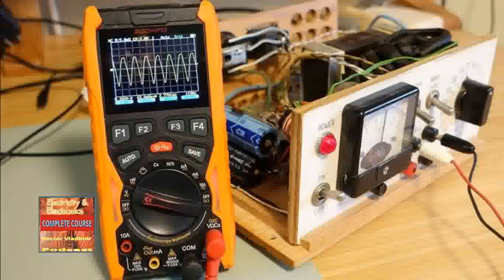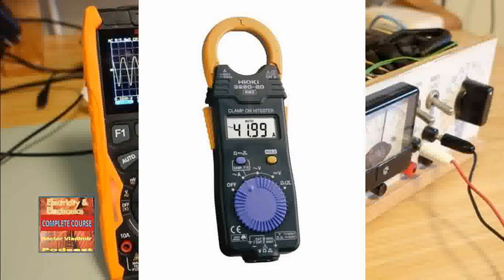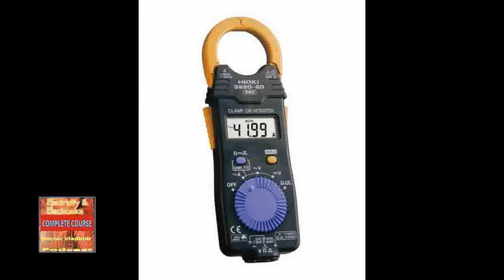To remedy this, a meter changes the AC voltage into DC by means of a rectifier. The rectifier is covered in detail in Chapter 17. For now, it is sufficient to say that a rectifier converts the applied AC current to a DC current of equal value. When the applied AC current is rectified to an equal DC value, the value is referred to as the RMS value. The abbreviation RMS stands for root mean square.